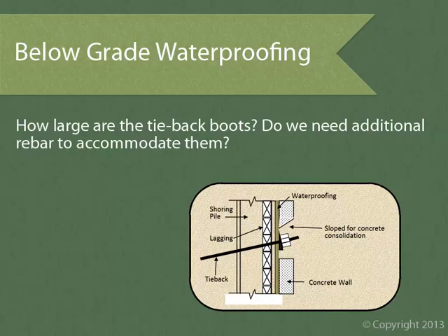If a backhoe hits and snaps a tension strand, we get what amounts to a small explosion that will send dirt and rock flying up into the air. This can seriously injure the laborer standing in the trench who's assisting the backhoe operator.